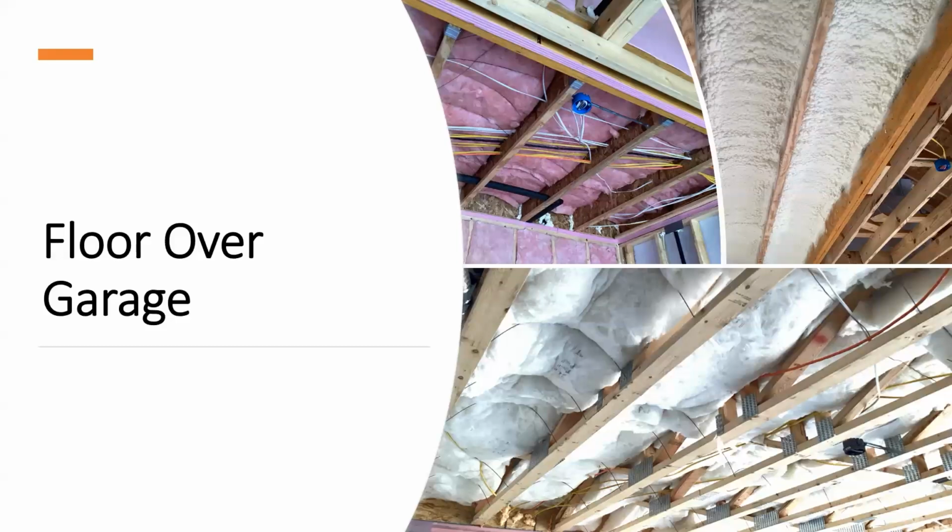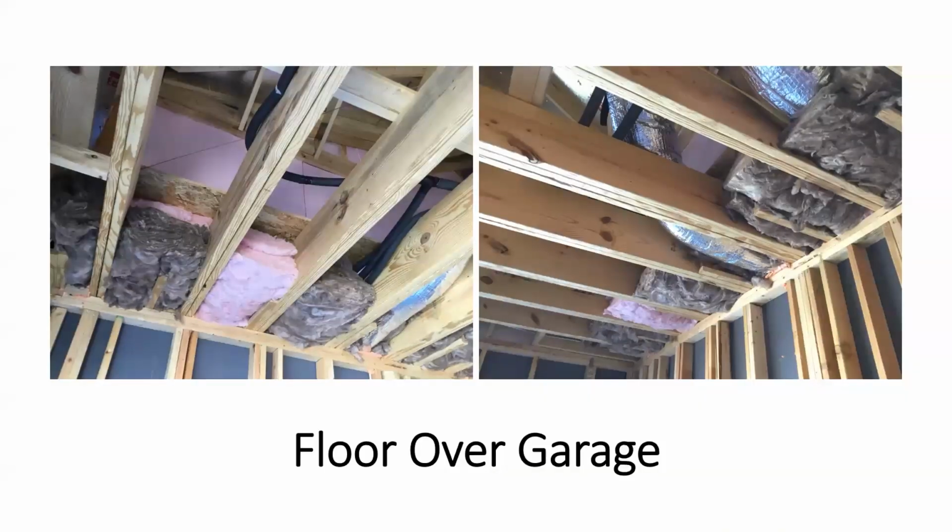With the foam, as we said earlier, once it's beyond 2 inches, it makes its own air barrier, so it doesn't necessarily need blocking on all the edges. All other flooring type material, bats, or anything that's netted and blown, all has to have air barriers on all 6 sides. And as Cody said earlier, it may not be in contact with the garage ceiling, but now code is getting to the point where it's addressing that and saying it doesn't have to be. As long as the R-value is there and not fully compressed or compressed very little, it's going to comply with that. And then don't forget these.